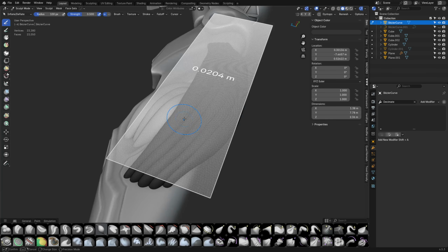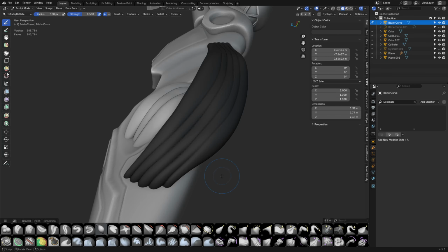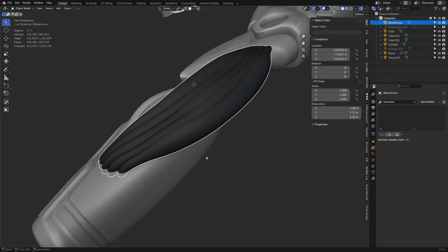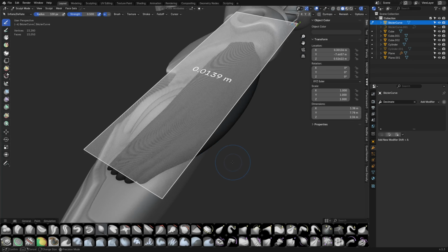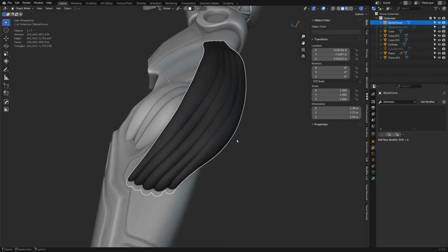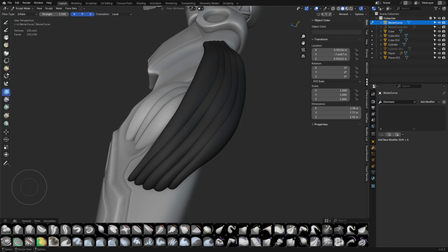And press R. Let's change that. Remesh. Golden now, right? So we could have done it at a higher resolution to maintain it a little bit more. But if we wanted to switch to voxel remesh, we could. I think the subdivision mesh would have been better, personally, so I would have probably just kept it. You can mix and match different topologies while doing concept design.